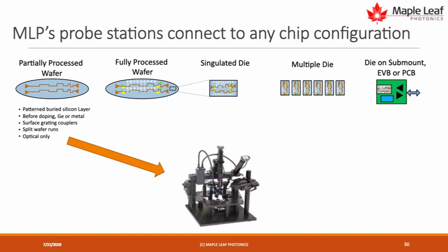Unfortunately, when you're going to do it this way, you can only have optical access to the chip. So you aren't going to have the metals that would allow you to bias things up. So it's really a passive view in, but it's a very early passive view, and you can save a lot of energy and time if you find something's wrong at that level.